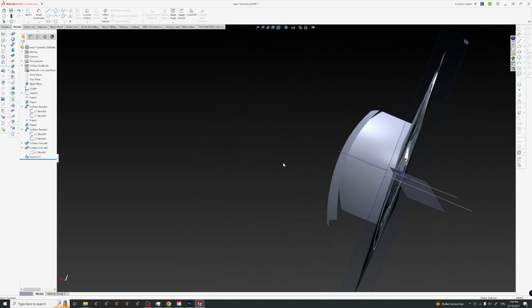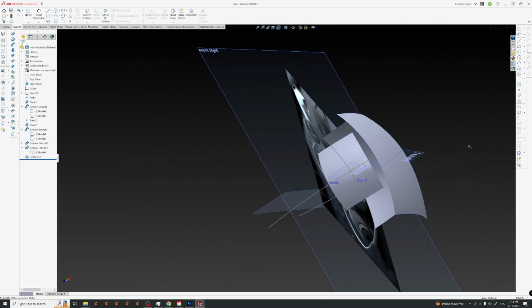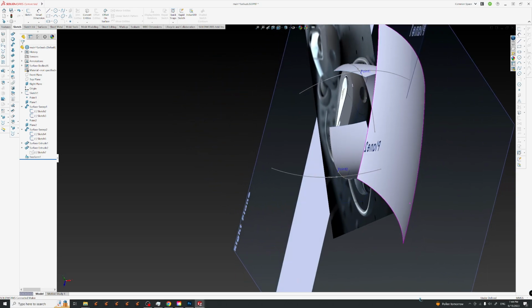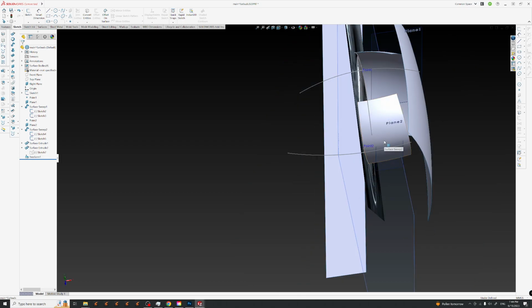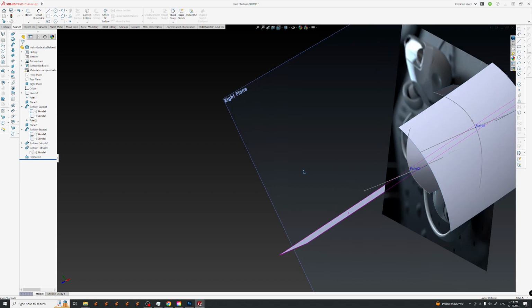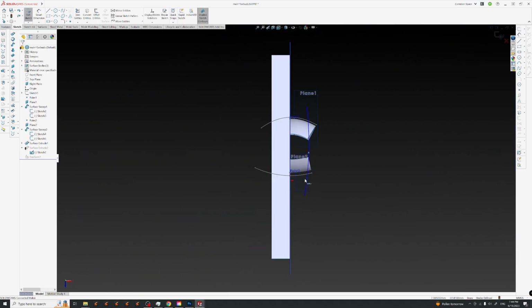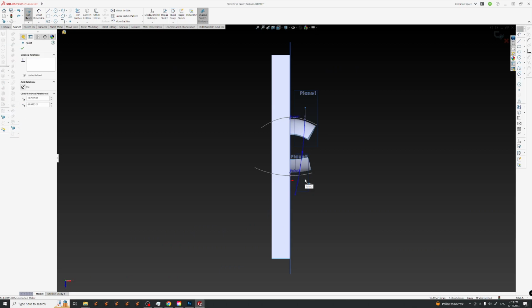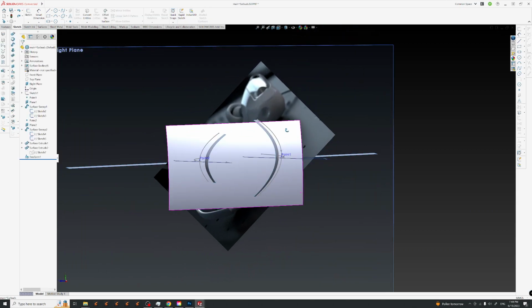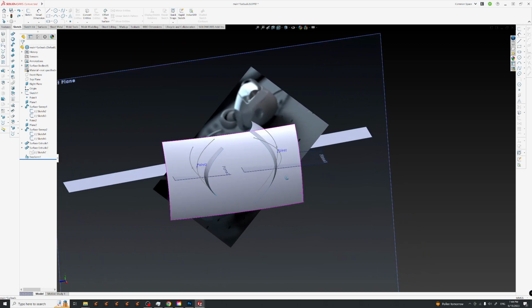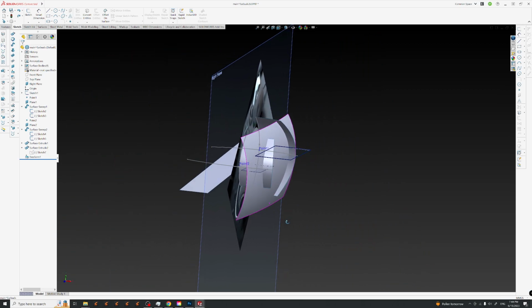So that means that we could get rid of one curve. Instead of making two curves to create a loft surface and then keep adjusting the curves around, we can really just create one surface and then just adjust the tangent handles, and that would be it.